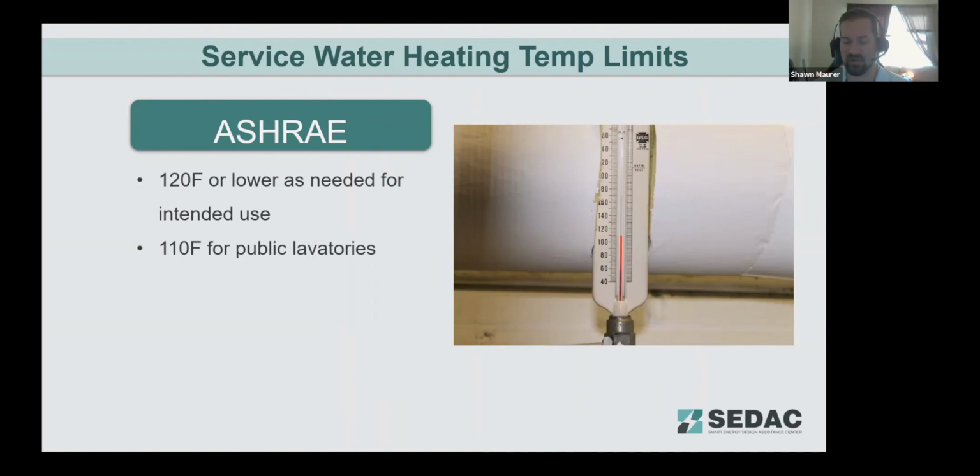Facilities with at-risk populations where you're worried about Legionella, you may be able to run higher service water temperatures, but you've got to have that mixing valve then to get that water down to these set point temperatures in the distribution system.